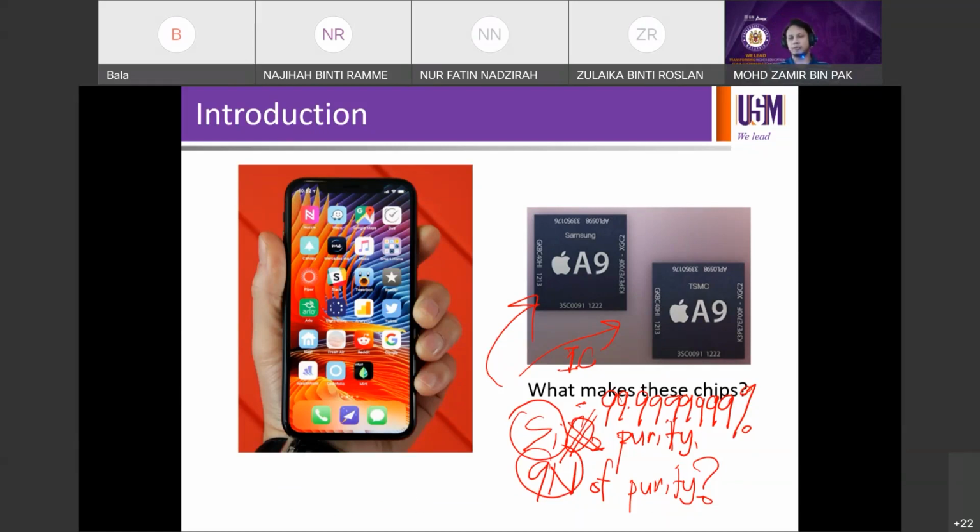On the other hand, if you talk about silicon-based solar cells, they still originate from silicon wafers, so you only need about 6N for the solar cells to work. So then you can already see what it takes for your transistors to work. You need to reach 9N or it won't work. On the other hand, if you work on silicon solar cells, 6N is already sufficient for it to work as a solar cell.